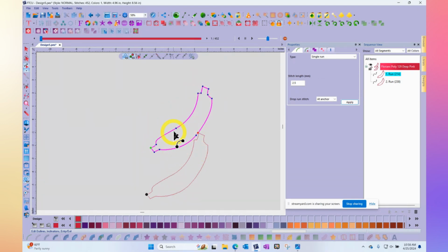It actually shows you the points that make up the banana. So if you want, you could somehow change the shape of your banana. But it also gives you the green entry and red exit points. And so what happened was, the original exit point was here and the software moved it to there. And it also moved, if I click on the other banana, the green entry point of the other banana to match up, so it found the closest point between the two.